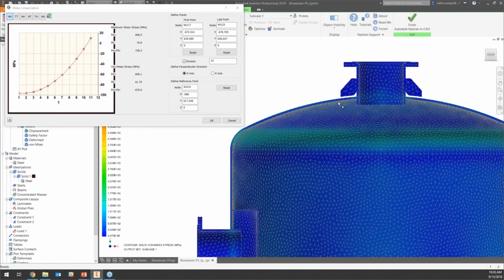So in those cases, you're going to have to connect the shell to the solid elements, which is never ideal. And secondly, the way membrane stresses on a shell element are calculated is very different than membrane stresses extrapolated from solid element results. So you will see some difference in results, and again, that's not really an apples to apples comparison with the pressure code. The entire idea behind this is to make sure that you have that apples to apples comparison. You're always looking at it on the same scale, so you can define your safety factors, etc.